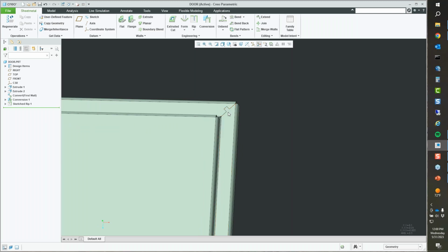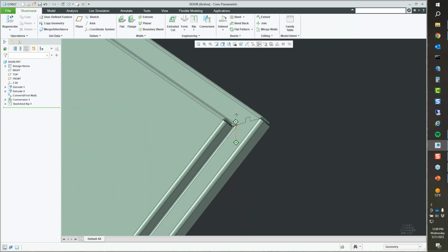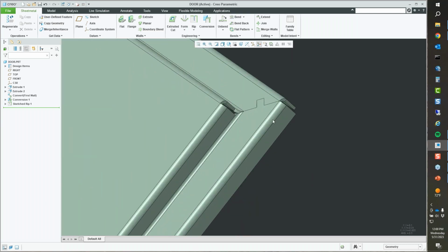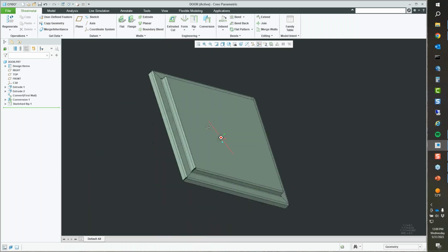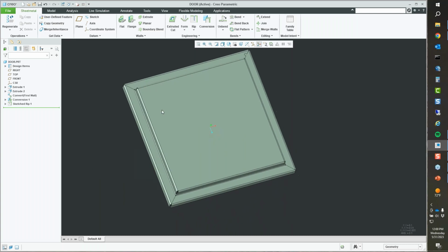Take a pair of vice grips and some sheet metal, kind of clamp them together and weld everything solid, right? That tells you, one, that you're punching and you're water jetting, however you're cutting the flat pattern, and your bends are all coming together using the right bend deductions, and everything worked out perfectly mathematically. And when they weld it up, you get a nice solid connection. So those are the very traditional reasons why you would use the 2 tools that convert from solid parts to sheet metal, and then the conversion tool, right?